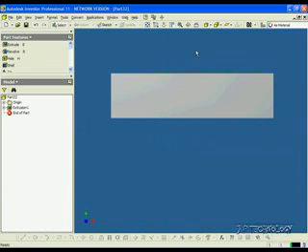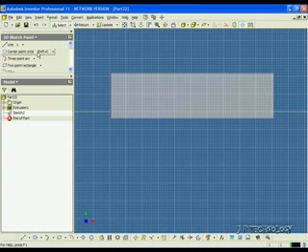Now to use the rectangular pattern feature, what you have to do first is create a feature, and then using that feature you're able to pattern it along an edge. So to start off, let's make our feature. So let's click the front face here, click Sketch, click the center point circle, and let's draw a circle in the top left corner here. Now let's click the dimensioning tool and let's make the diameter of this circle 10 millimeters, and let's make it 10 millimeters from each side.